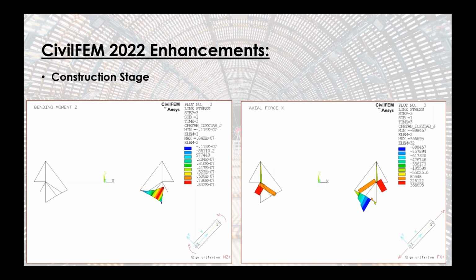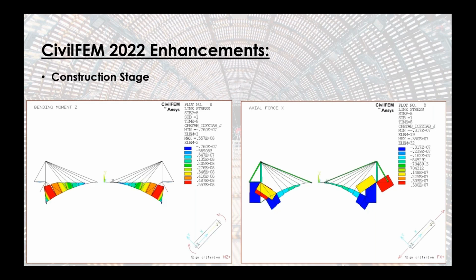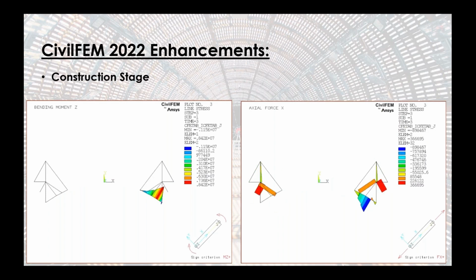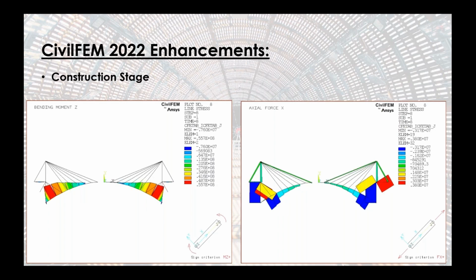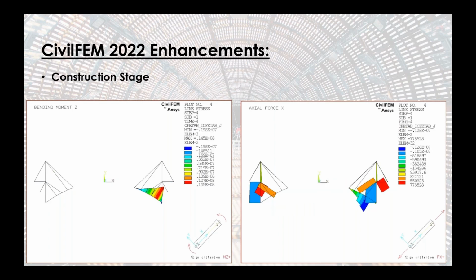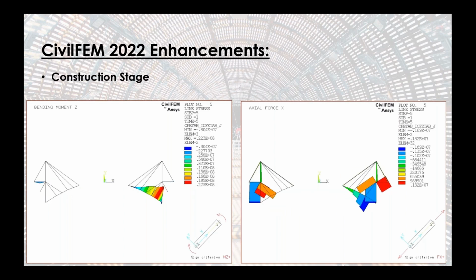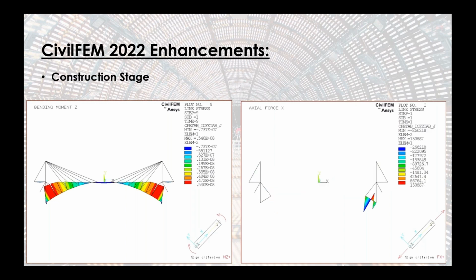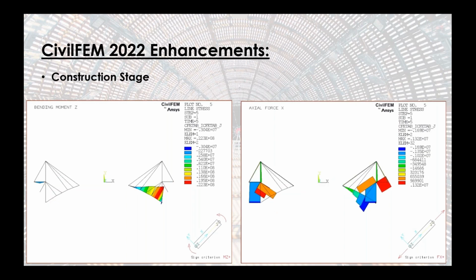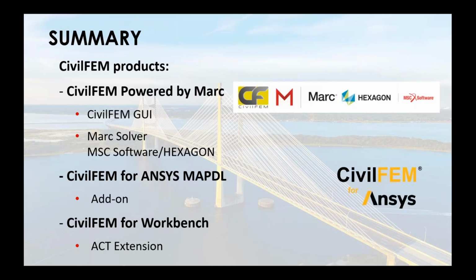So with this tool, you can see we can create and design any type of concrete beam cross-section with CivilFEM, also considering not only calculating mechanical reinforcement due to the forces we have, but also considering minimum and maximum reinforcement amount the user could define. And today we just show the beam elements, but of course, in the current version, you can design shell elements as well, and solid elements, but that will be shown in another webinar.